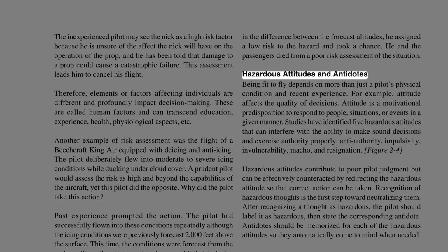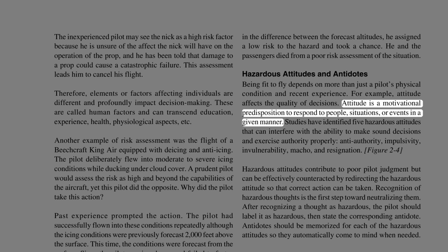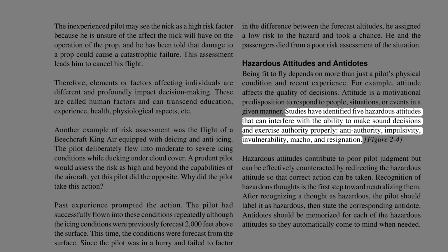Hazardous attitudes and antidotes. Being fit to fly depends on more than just a pilot's physical condition and recent experience. For example, attitude affects the quality of decisions. Attitude is a motivational predisposition to respond to people, situations, or events in a given manner. Studies have identified 5 hazardous attitudes that can interfere with the ability to make sound decisions and exercise authority properly: anti-authority, impulsivity, invulnerability, macho, and resignation.